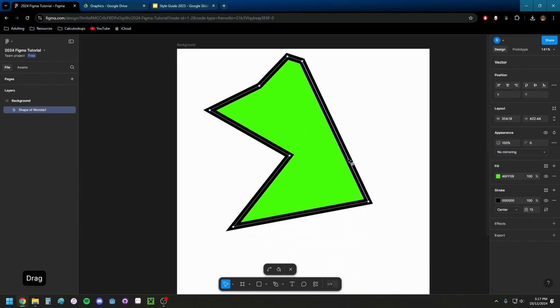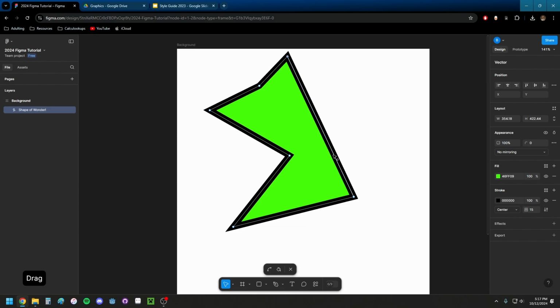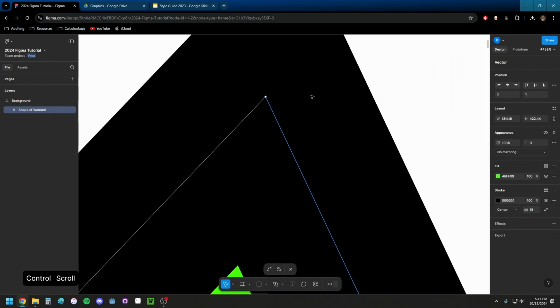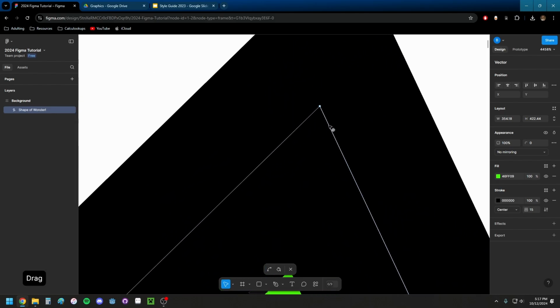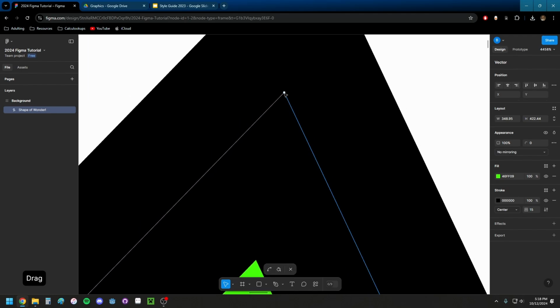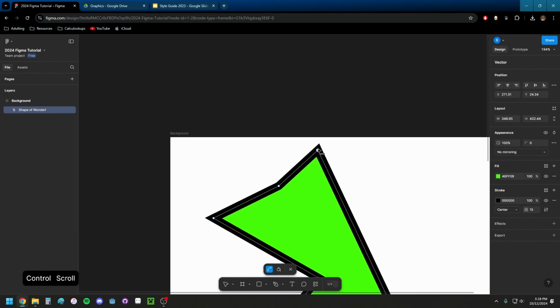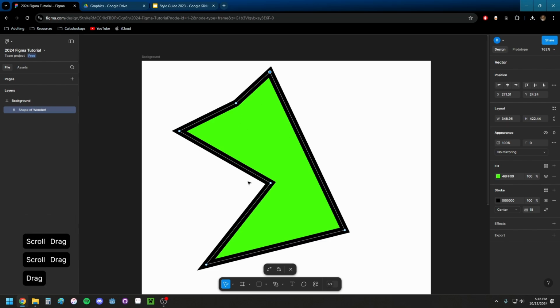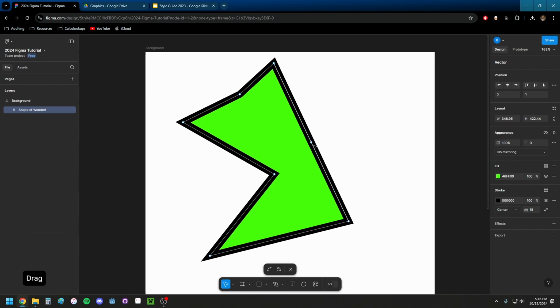It can be a little weird because if I put these two nodes on top of each other, sometimes there'll be two nodes there instead of just one, and that gets a little funky. So just be aware when you're doing that. We don't want to have a bunch of geometry overlapping itself. We might get strange results, so just be careful.